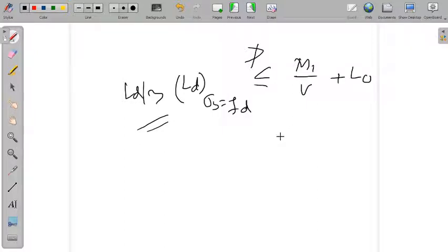What is fd actually? fd is nothing but 0.87 fy, so the stress in the reinforcement is going to be 0.87 fy. Full stress on reinforcement is being talked about, as fd is 0.87 fy in case of limit state design. In case of working stress design it is different, and that we have to check. I am not writing it here.